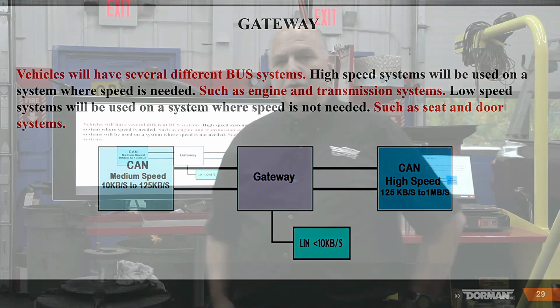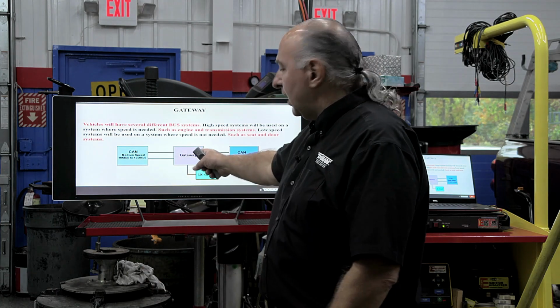What vehicle do you have issues with communicating because of the gateway module? What year did it start? So you could be on a popular brand car manufacturer, and the issue you have is when you plug your scan tool in and you didn't go to www.autoauth.com to register your tool for 50 bucks. Any aftermarket scan tool that goes online, guess what? You're going to need that because they'll lock you out of that gateway module.